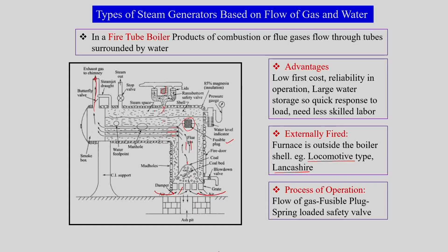If the steam pressure is higher than the expected value, it will cross the spring force, and this will open the lid of the valve, and steam would flow out till the pressure gets equilibrated. So, the pressure safety valve is useful for control of pressure, and the fusible plug is useful for control of temperature.